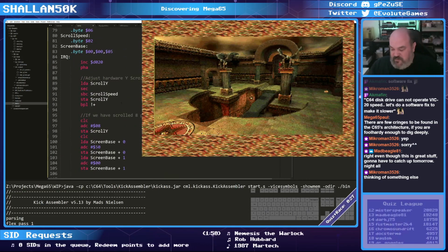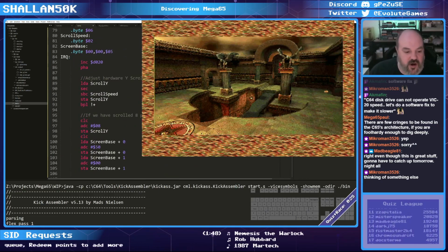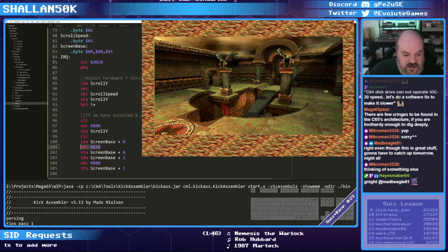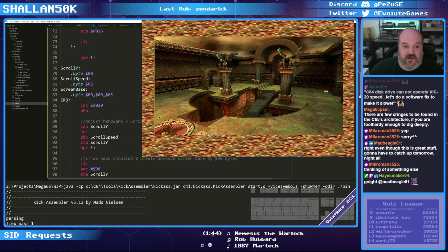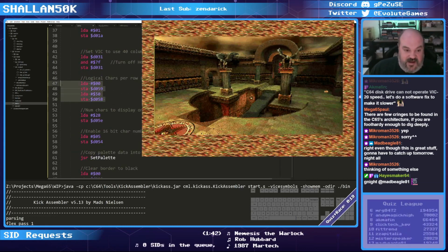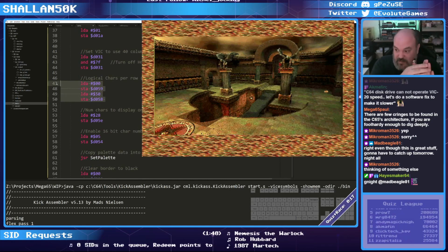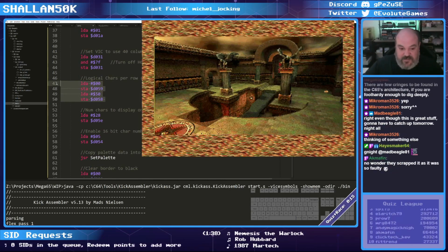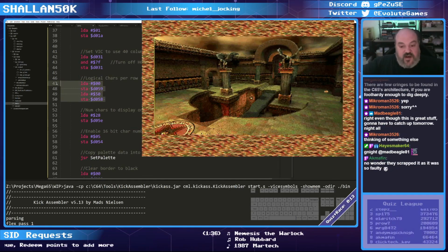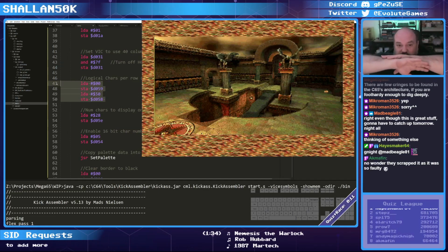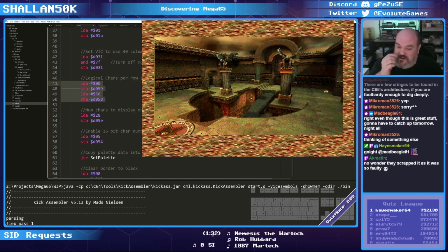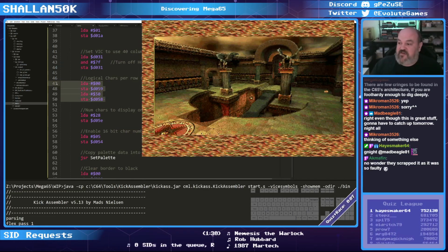But every time we move the screen up by 1 row, all I do is go in and add 80 characters to that screen row. I add 80 characters because that is our logical characters per row. That's how many memory addresses are taken up by that. And I can move the entire screen up by 1 without shifting anything in memory. All I'm doing is saying, this is where the new screen starts.